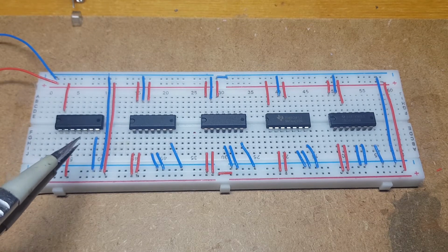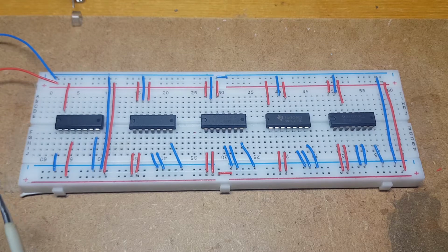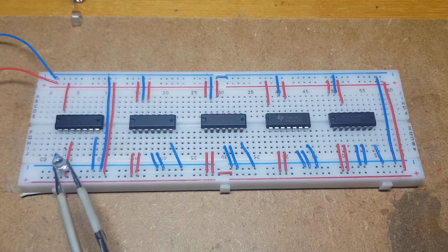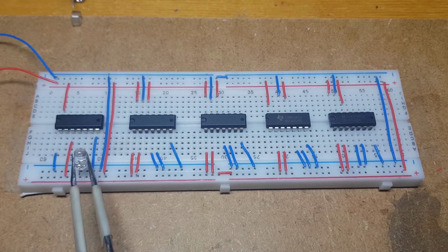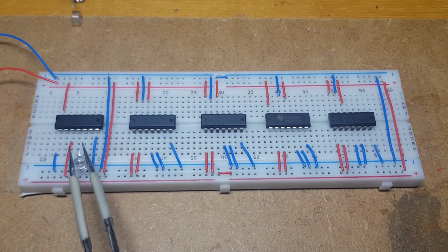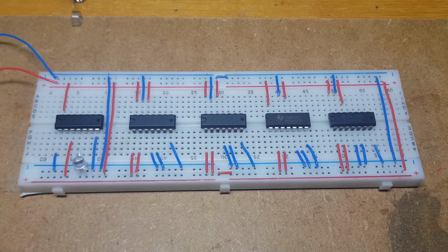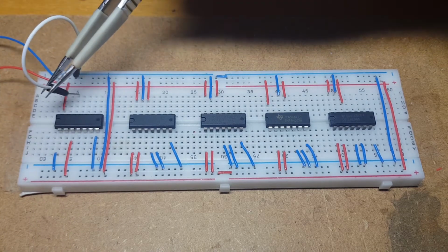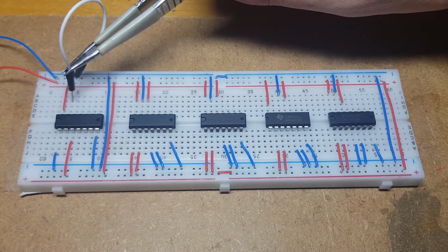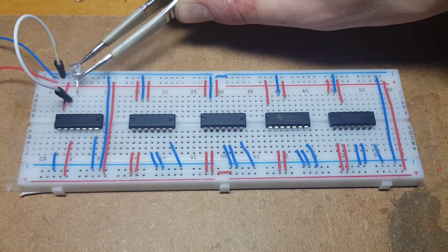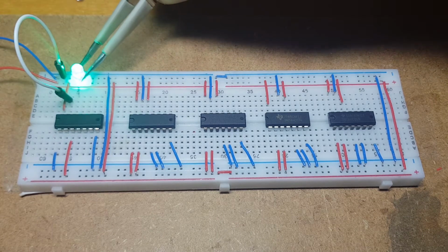So at the first pin, the input is low, so the output is high on the second pin, as the LED shows by shining. On the third pin, the input is high, so the output on the fourth is low. Here I am using jumper cables to directly give high or low input, and as before, when the input is high, the output is low, and the other way around.